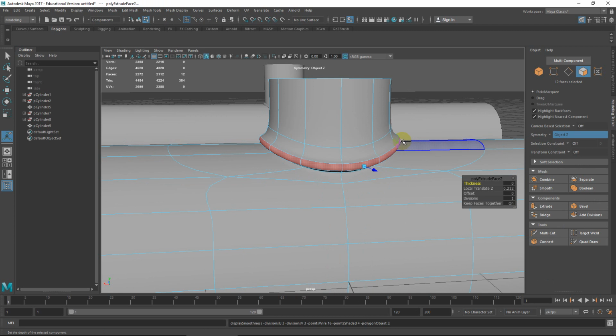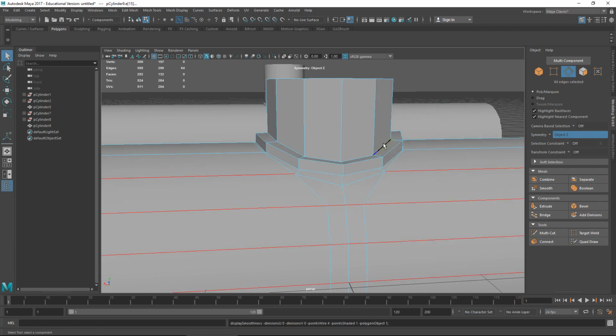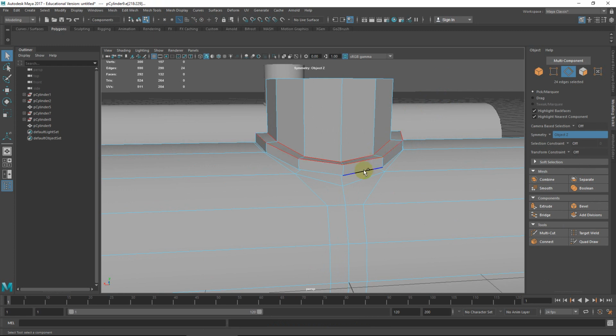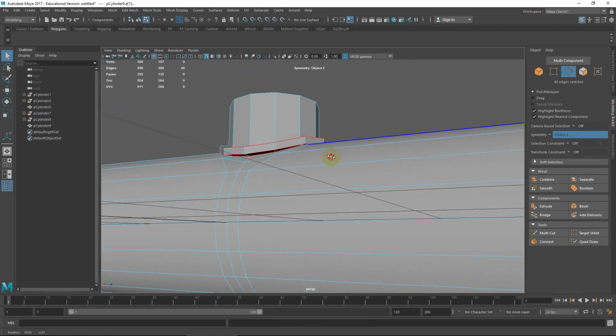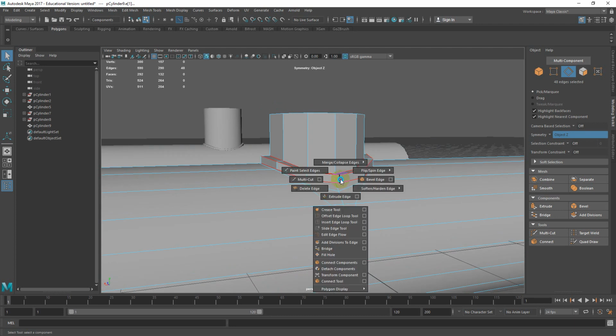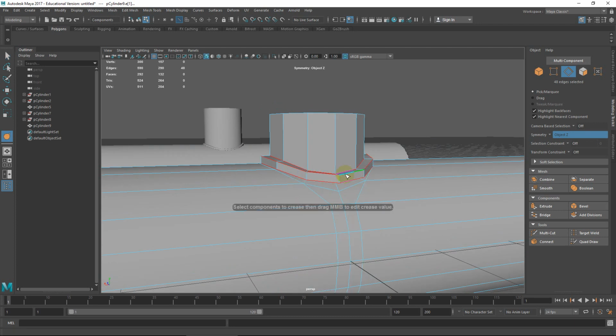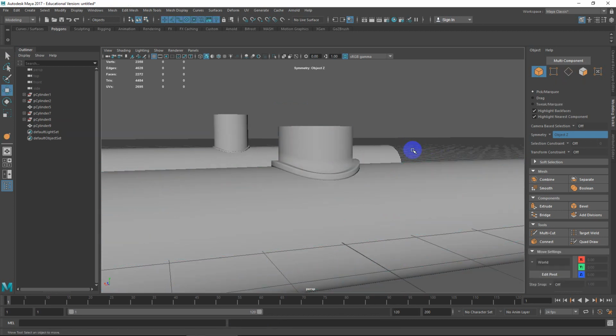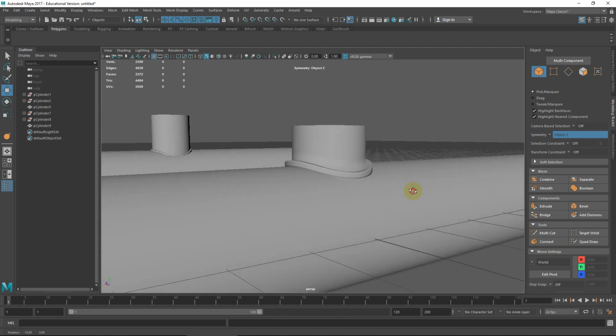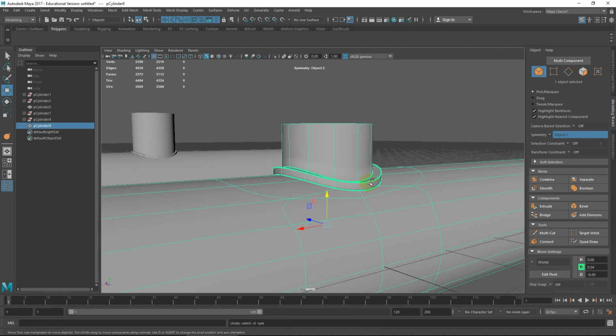Now if we smooth this, it's going to look super weird, right? So that's just hitting 3. So a lot of times what you need to do is add either a creasing. So I'm going to go in across here and do that. I can either do the Crease Tool. So I'll show you what that looks like. If I middle mouse click and drag, it creates a kind of faux sharpness, right? So that's one way to do that.